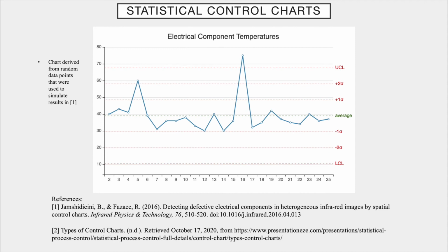The use of the control charts when analyzing thermograms helps better identify if there are problems that tend to happen quite frequently that can be corrected by changes in the production or installation process. Not addressing these issues in the components could result in damaging entire machines and increases the risk of fire since we are dealing with electrical currents after all.